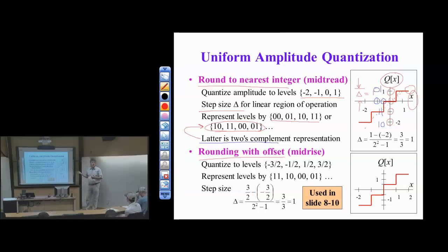This becomes our new noise floor in many cases. It's more noise than thermal noise. The ideal case is to match the quantization error with the thermal noise, be right at the noise floor, and then we don't add any noise to the system. That's nice when we can do it. But the main thing is just convenience. It allows us to do inexpensive calculations. Now we can do everything in discrete time and digital, take advantage of Moore's law, programmability, configurability, easier to update, upgrade, fix, maintain.